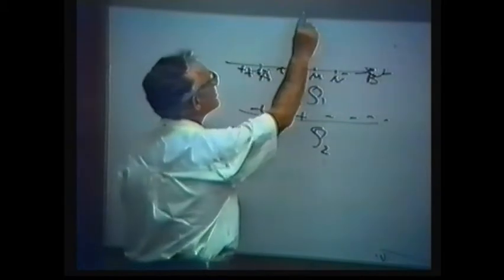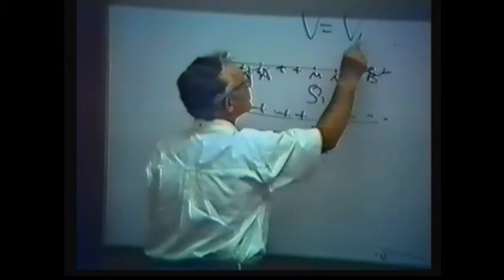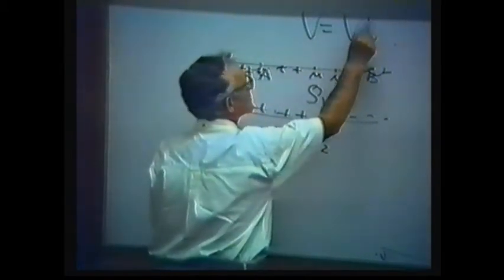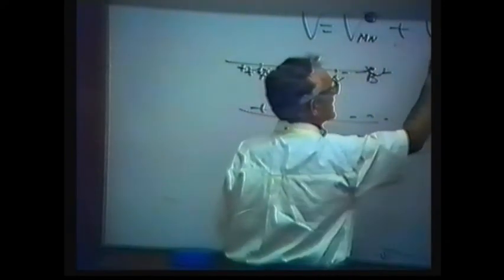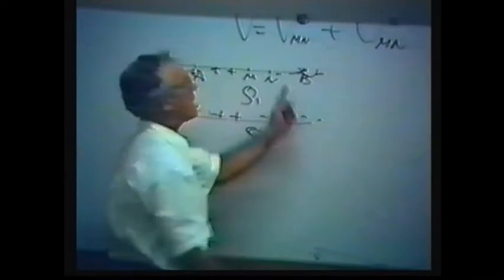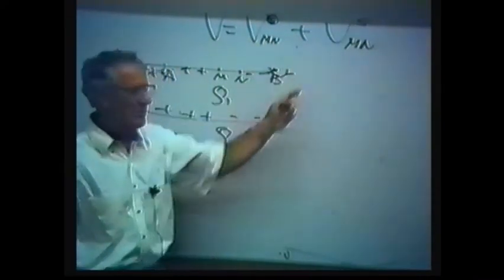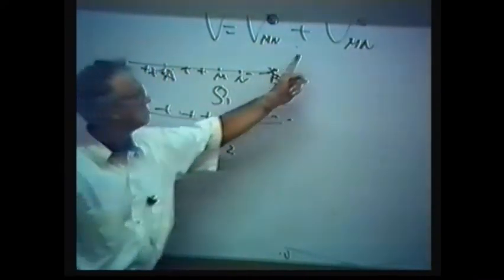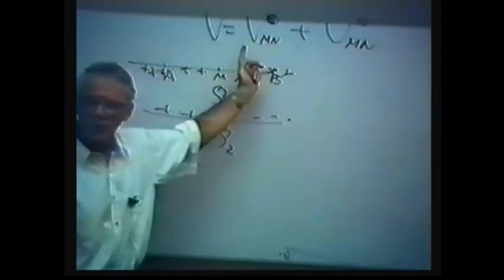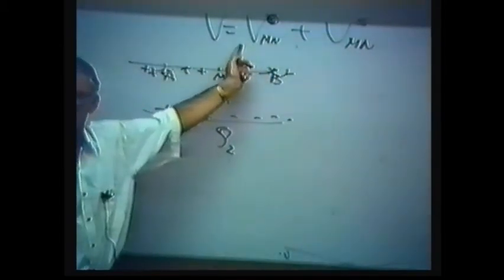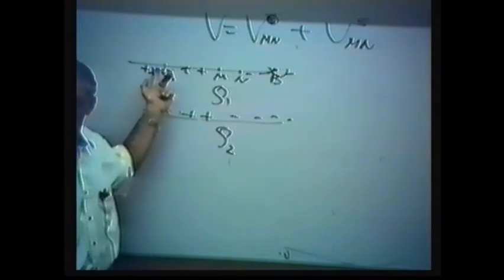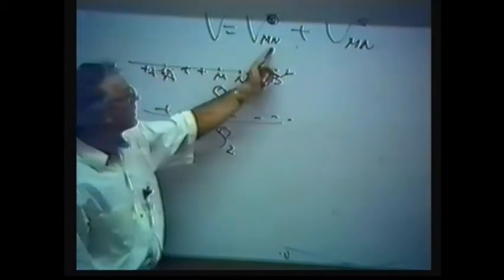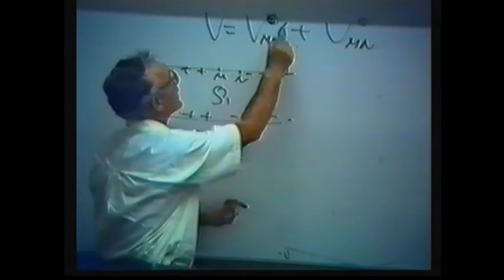We measure total voltage due to electrodes, primary field, plus secondary field. Which part contains information about rho 2? This part. This part depends on what? Rho 1 due to electrode. We know this part. It's a function of rho 1.